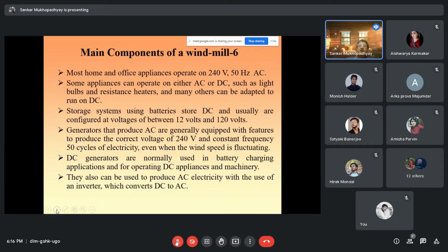turbine. Now suppose the speed was in the range of say 100 to 120 rpm, and it is increased by 10 times so that it becomes close to 1200 rpm at the end. The 1200 rpm to 1500 rpm is the rated rpm of the generator, and the generator voltage is capable of taking that fluctuation. 1200 or 1400 to 1500, that is the gearbox ratio at the end.